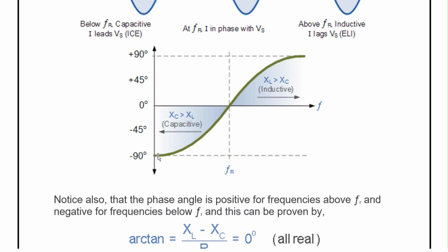And as you increase the frequency, the capacitive nature is reducing, and so it is reaching the point of frequency where they are equal. And after that, the circuit becomes inductive, and the current becomes lagging by an angle starting from 0, gradually increasing and going up to 90 degree.